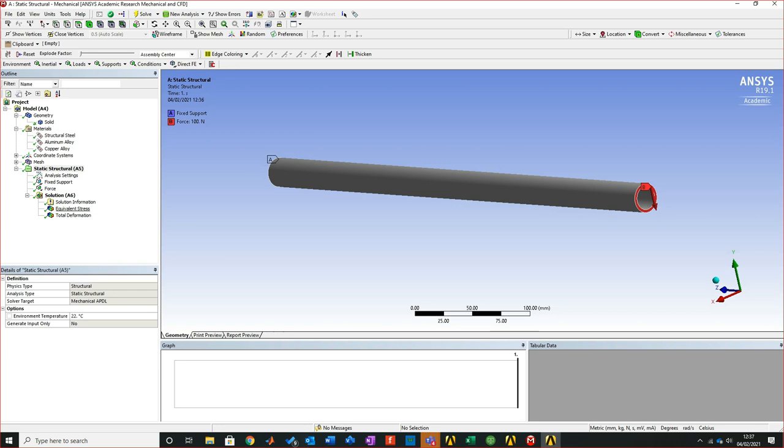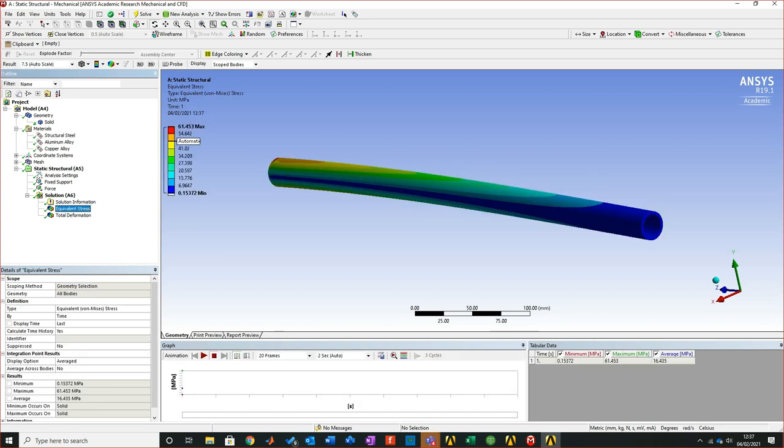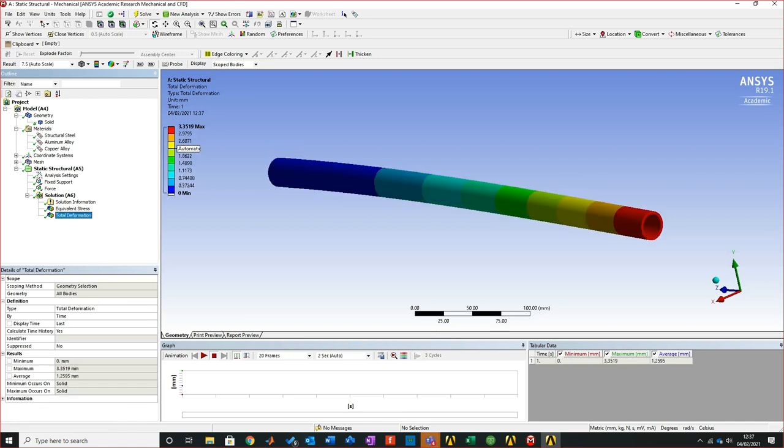So onto my copper. Yeah, now we brought that value down a little bit. It's still obviously nowhere like structural steel, but we brought that value down just a tad, not much. The deflection is much less. I'd never really advise copper for a road bike, but it just starts to introduce the idea of testing for different materials, looking at the types of things that I'm getting.